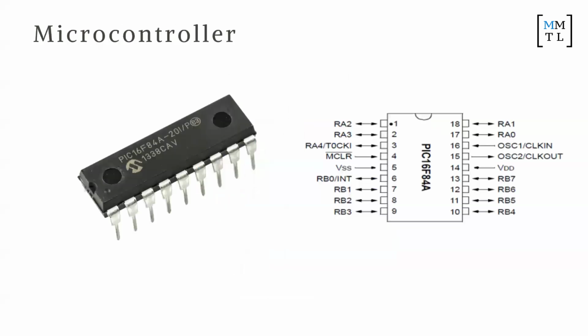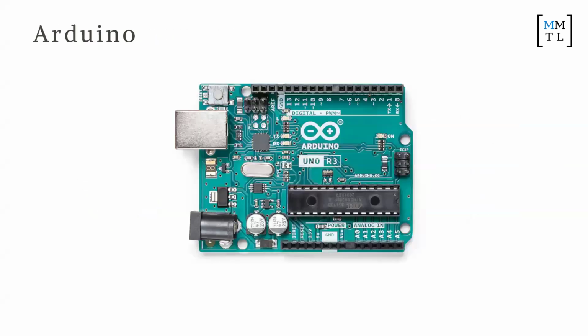All right, so this is a microcontroller. This is what you'll see on the main part of the Arduino, a little microcontroller there. It has a number of pins, and some microcontrollers have this little notch here to indicate the orientation of the microcontroller. These pins all have completely different functionalities, so they're not interchangeable. If you do something on pin 7, sometimes you can't do it on pin 6. So you have to be careful and read the manual.